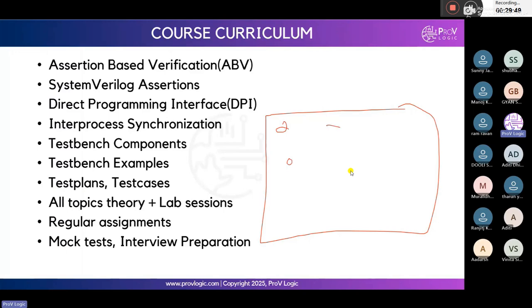Suppose here there will be a processor, memory, controller, and some other IP, right? Whatever we are connecting here to here and here to here, these all will be connected to the cross trigger network, and here there will be debug units. This whole setup can be done in post-silicon. According to that team, we do the verification test cases; everything is different. Pre-silicon and post-silicon, everything is different. In pre-silicon, we don't have this type of hardware or this type of setup. Majorly, we connect with the Wombat and to the computer.